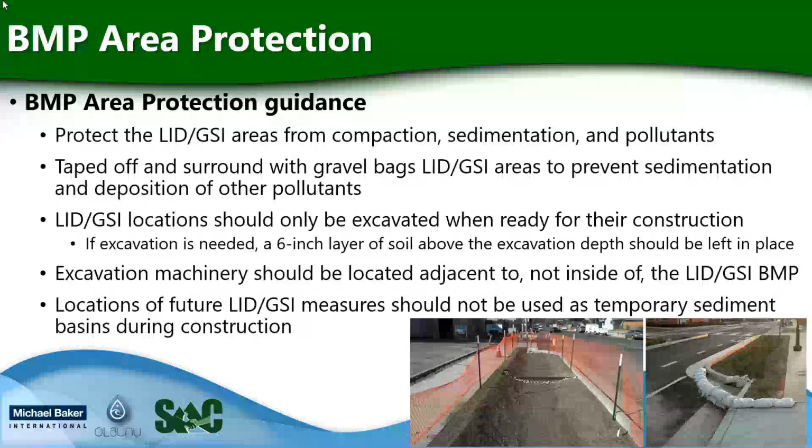Location of the future LID and GSI measures should not be used as temporary sediment basins during construction. Even though many of these sites are in low spots, using them as sediment basins will affect the long-term infiltration and viability of these locations.